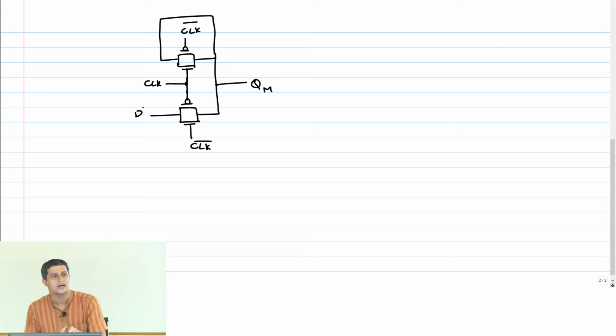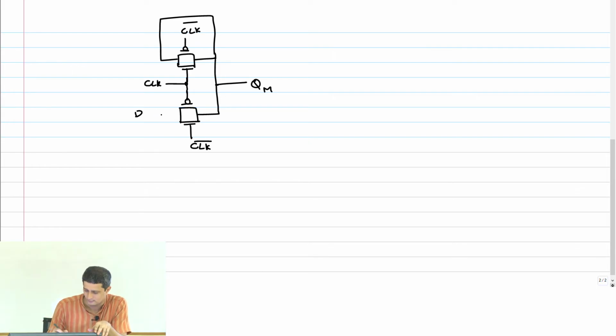Here, when I try to characterize, I need to know where this flop has been placed. Without that, I cannot tell you, and therefore I cannot design a standard cell element like this. In some special places you are free to place this circuit as it is and get it to work. But in order to characterize it, I need to drive it through inverters, so that I can tell you exactly what the delays are.